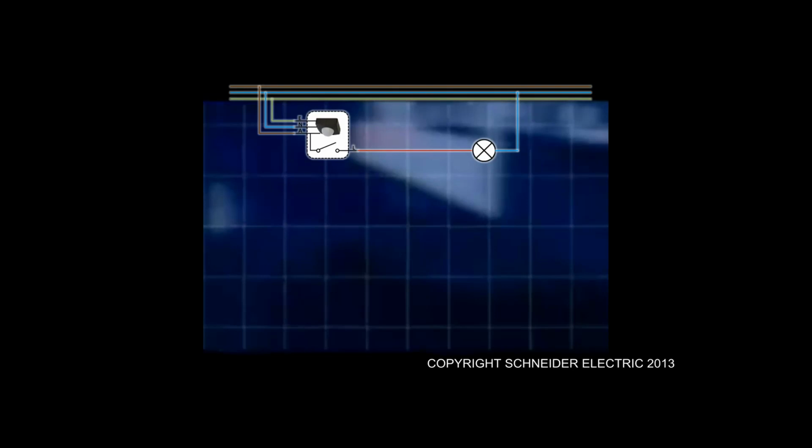Now, with this particular type of sensor, there are two dials. You've got a light lux level setting, as well as a duration or a time setting. What we're going to be looking at right now is the light level setting. So currently it's set to 1000 lux.